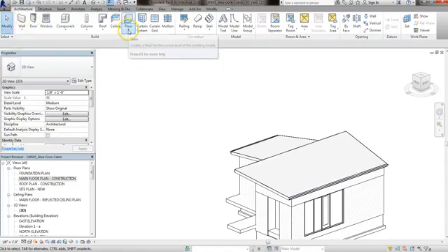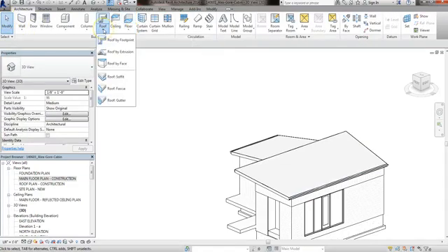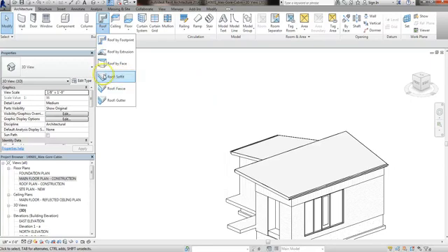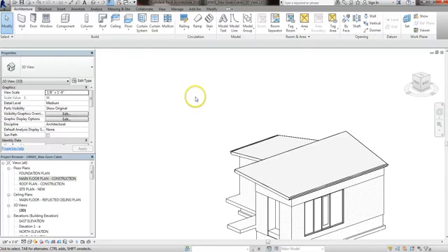And the other thing, which we won't be doing, but just so you guys know, there's the soffit, and those are created just like roofs. So if you look in here, it goes into sketch mode. You can create the soffits. You can create them either horizontally, or you can actually apply a slope to them too if you want them. And then you can, if you put those, you can schedule those out too.